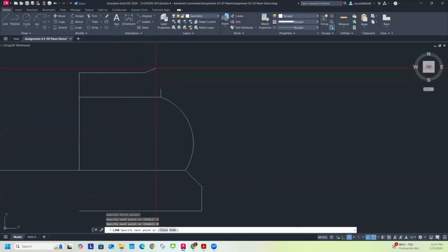And then so I'm in line actually. Let me just show you with polyline. So I'm going to go up 3 once again because 2 plus 1. I'm going to go over 8. And then now, because I'm in polyline, specify next point or, and it gives some options. I can choose arc. And then I'll escape. So just very easily made an arc right there.